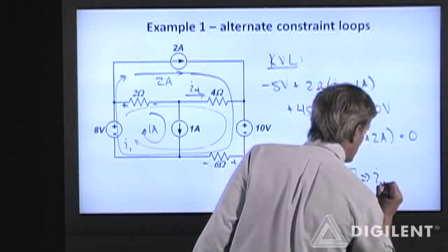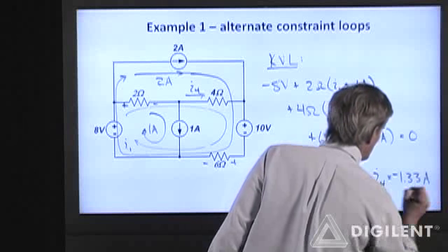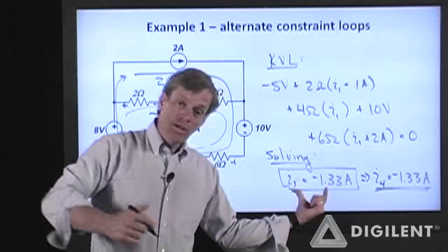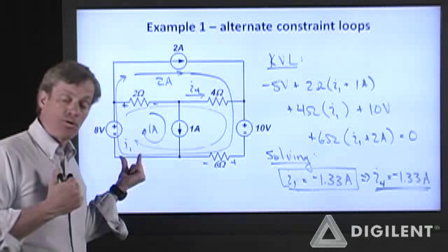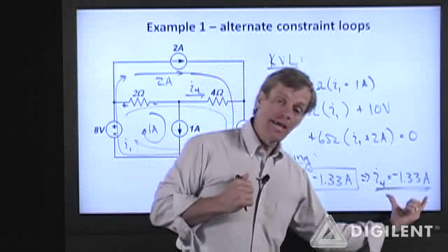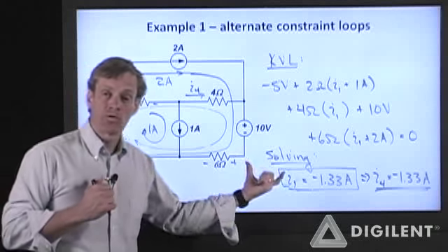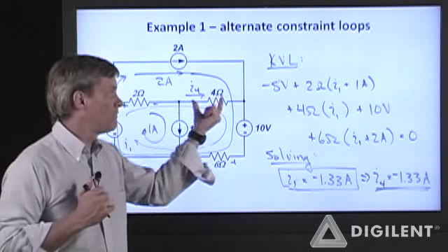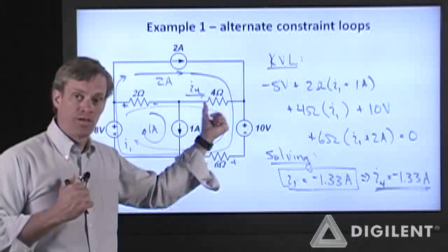So in this particular case, I4 is equal to I1, which is minus 1.33 amps. My mesh current was not the same value as the mesh current for the previous choice of constrained loops. However, my final physical current between the two choices of constrained loops is the same, because you've no longer put any constrained currents through this resistor.